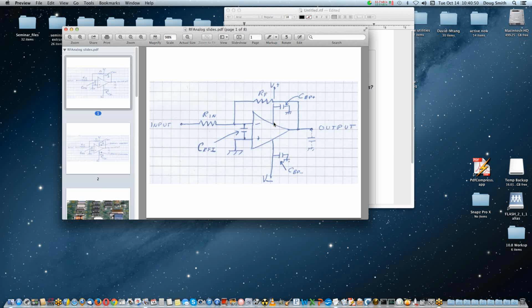We did have a comment from an attendee who said that they've worked with analog op amps, and in their case, they've been able to use their feedback network to implement an appropriate narrow band filter to pass the appropriate signal and block the rest. Do you have any thoughts on that? That would work up to a point, but when you're talking about 2 gigahertz, I bet that feedback network's not characterized at 2 gigahertz, and the op amp doesn't even act like an op amp at 2 gigahertz. So I'm not sure that you can handle it by feedback for that.